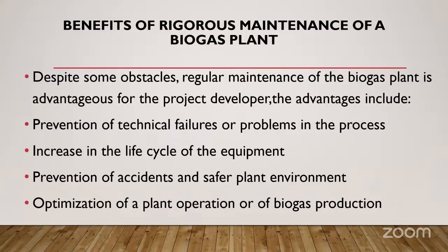So how to maintain biogas? We said we have to do regular maintenance, which is routine maintenance. You can do it by interval time. You ensure, for instance, that after a certain amount of gas release, you do maintenance. Or you can say after a given time, let's say 100 hours, 2,000 hours, you just do a regular maintenance. And that one is going to be a routine maintenance.